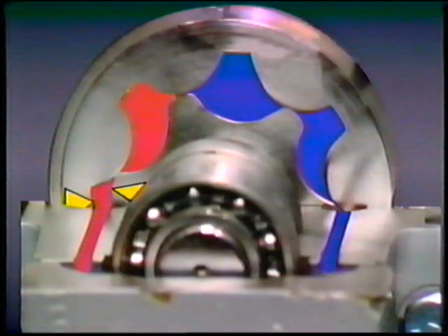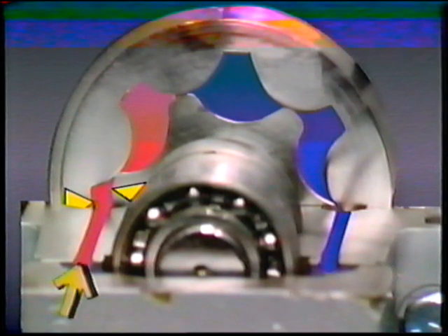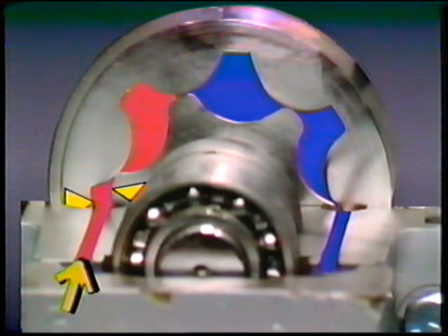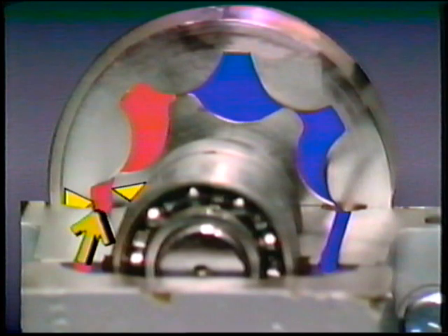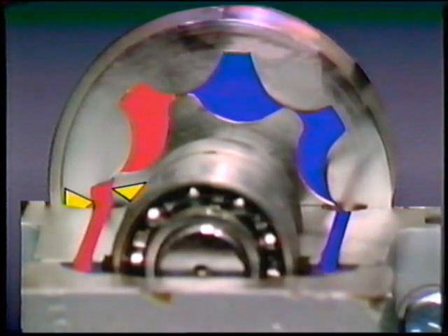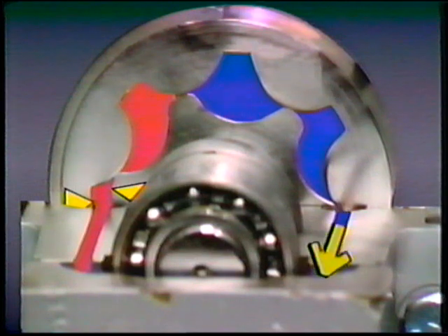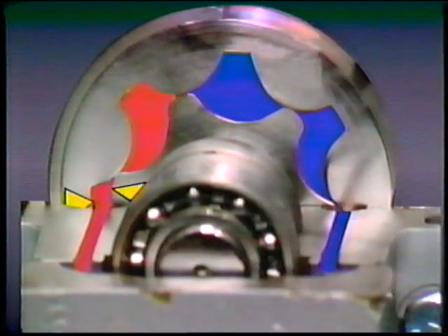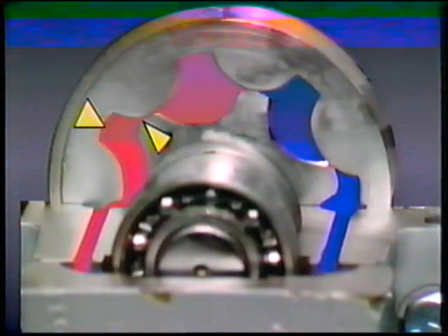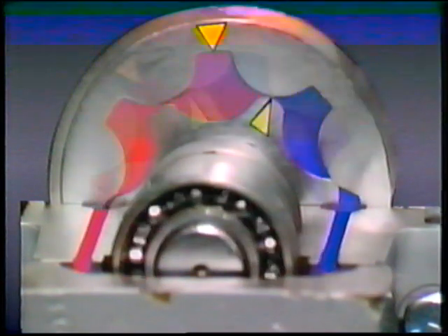The movement of the gears in the gerotor motor is similar to the gerotor pump. Pressurized fluid enters the port plate, pushing on one side of one tooth of both the inner and the outer gear. Since fluid on the outlet side is allowed to exit through the outlet port, there is very little pressure to oppose the gear movement, and both gears rotate.